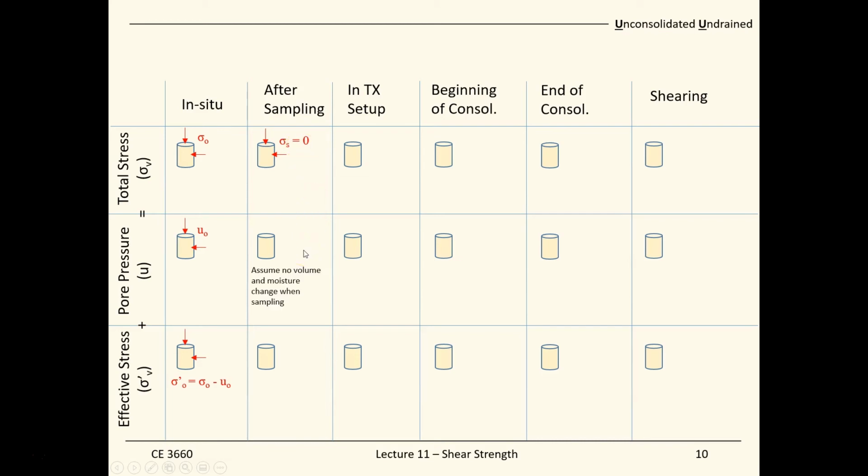But you realize that for clay samples, even though we remove all the confining stress, a clay sample can still be cohesive and hold itself. It is because there is a suction force provided as a pore pressure to keep the samples intact. We assume all the original vertical stress now becomes a negative pore pressure that is able to hold the samples together.